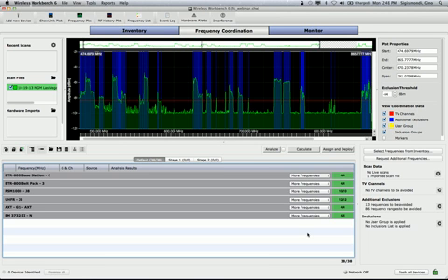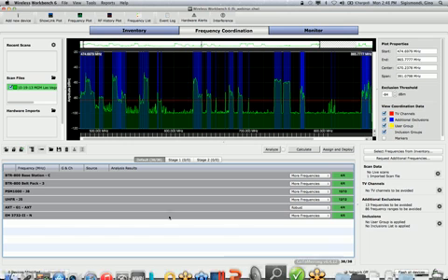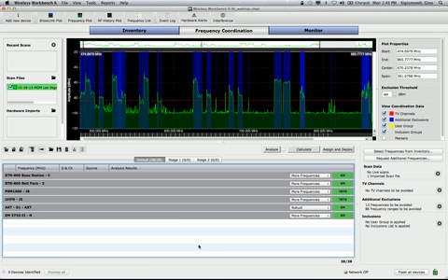And you could do the opposite if you were in a more ideal situation and make it more robust if you wanted to, correct? That's a great question, Cheryl. Yeah, absolutely you could. So let's say some of our frequencies, let's say for our Axient system, are corresponding to a VIP talent or mission critical channels that need as much space as possible. You can totally change those things, such that the channels that need the most robust performance get the most robust frequencies. And that flexibility is built right in there. That's just one of the tools you've got to adjust how your frequencies are compatibly found.